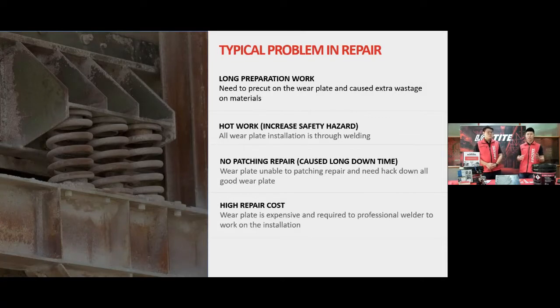Next, the installation of these wear plates involves welding, and welding is a type of hot work. In certain industries, they are very particular about hot work, because it increases the safety hazard in their plants. Next, by using these wear plates, we can't do any patching repair. What I mean is, whenever part of a wear plate is really damaged, we need to hack the whole plate down rather than do patching repair. All this costs additional time in your maintenance process,